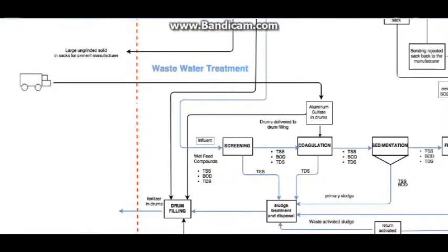Screening. The wastewater coming from the mixer is fed into the wastewater treatment facility. The wastewater contains high BOD, TSS, and TDS. The screen is used to separate larger suspended solids from the water.